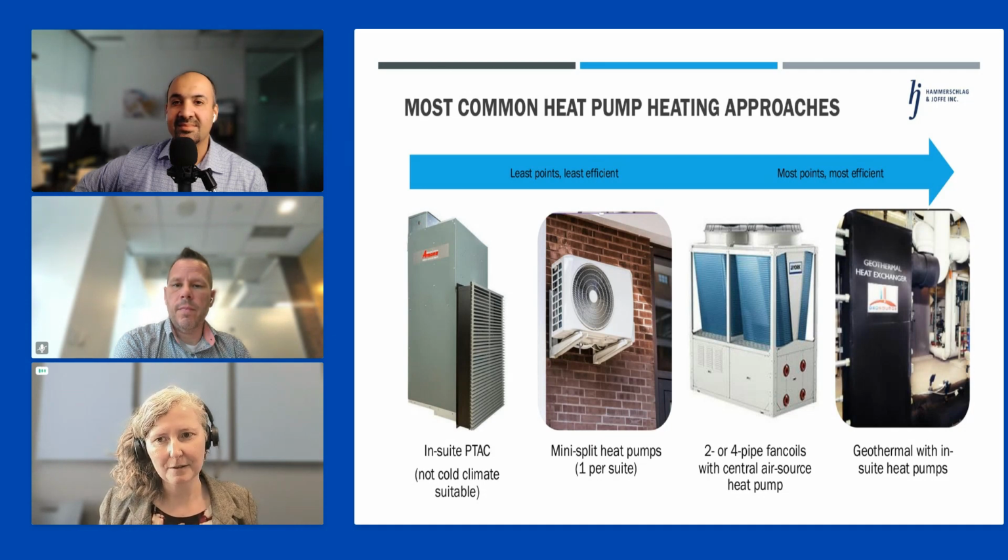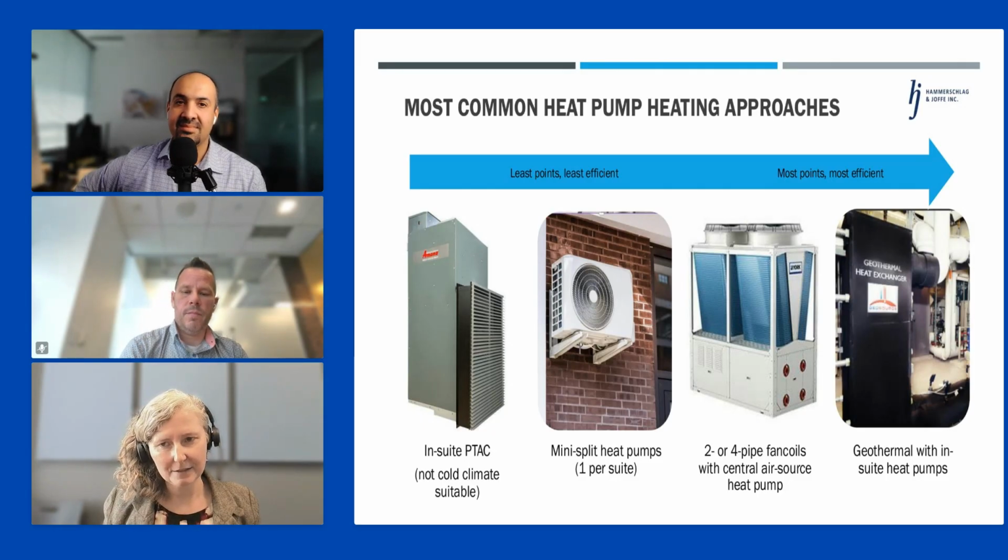heat pumps. So for larger projects, that's a vertical stacked. For smaller ones, there's a variety of unitary equipment. So these will be drilled into 300 to 650-foot wells below the property. There's a lot of practice in the GTA with putting those under the footprint of the building. So they'll often come in first before the rest of the building has been constructed.